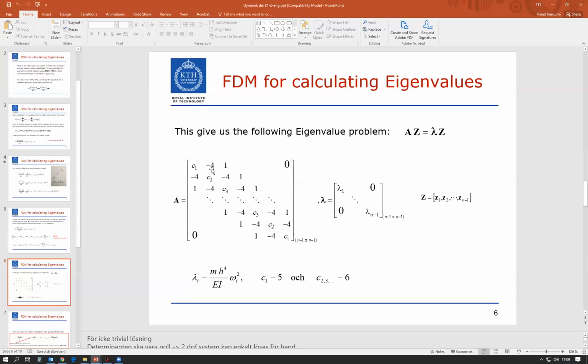So what we do is construct this matrix A, and then send it to the eig function in MATLAB, and the result will be the mode shapes and the eigenfrequencies. What is particular about this matrix A, as you will see soon, is that the first off-diagonals always have a number 4, and the second off-diagonals always have a number 1. The rest will be zeros.